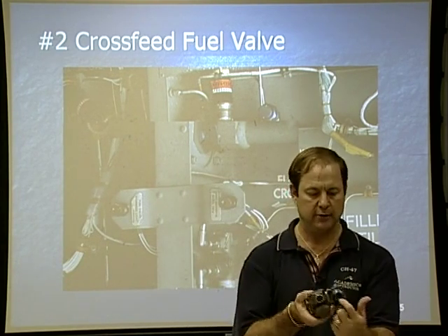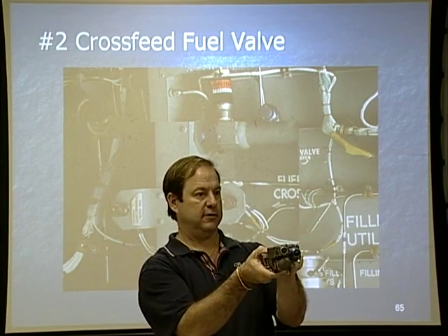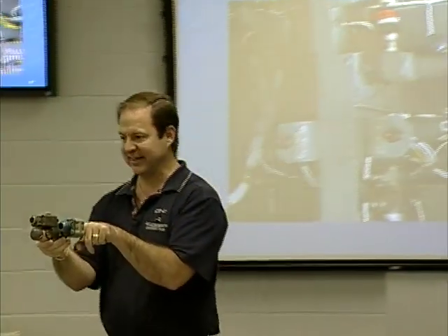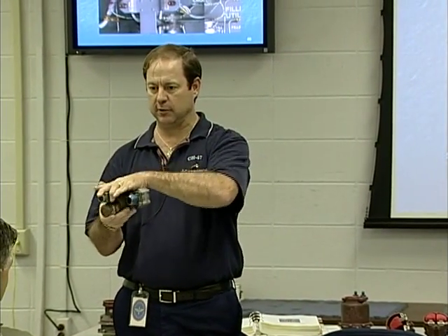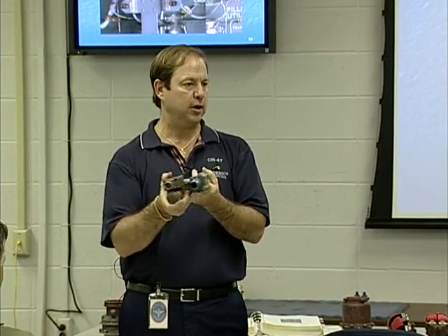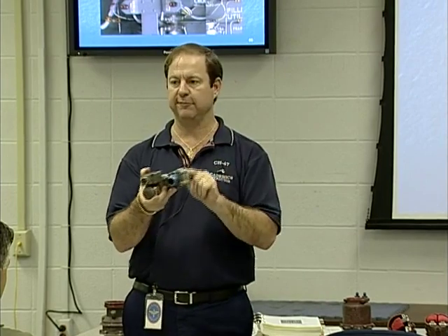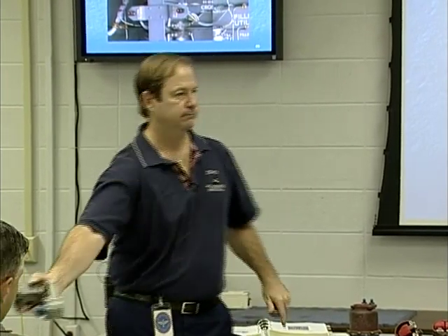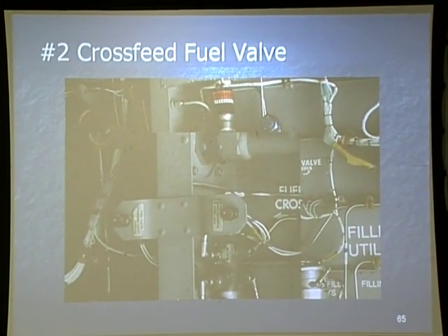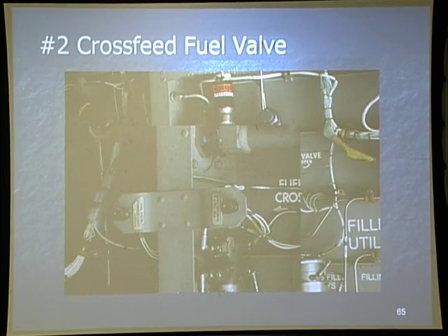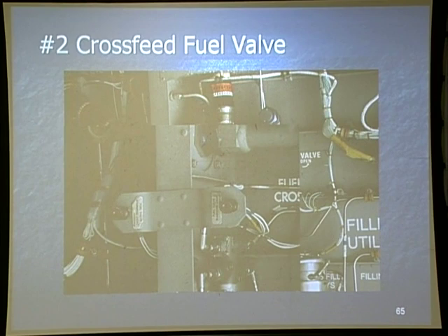And what you're talking about is a valve that slides out of the way like a guillotine. If I were to slide it, you'd see a piece of sheet metal come across that closes it up, and it's sealed, and that stops the fuel from being able to go through there. Good? But now, you'll notice I was playing with a handle. Those valves are also, in the case of an electrical failure, something we can manually operate from the rear of the aircraft. Any questions about that?